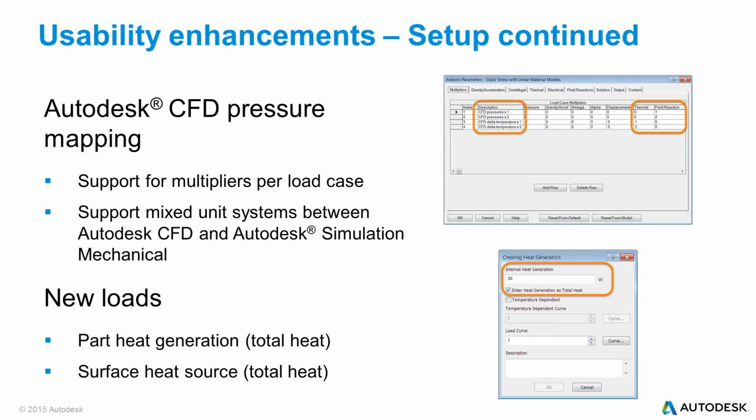But if you hand build a mesh, we will not be able to find the centroid point for a given surface on a hand build mesh. And of course, if you hand build a mesh, there is no such thing as an edge, right? So we can't use the centroid creator to create the center of a hand build object. I hope that answers that question. All right, so I see that we're in the CFD pressure slide, so I'll continue from there if that's okay.